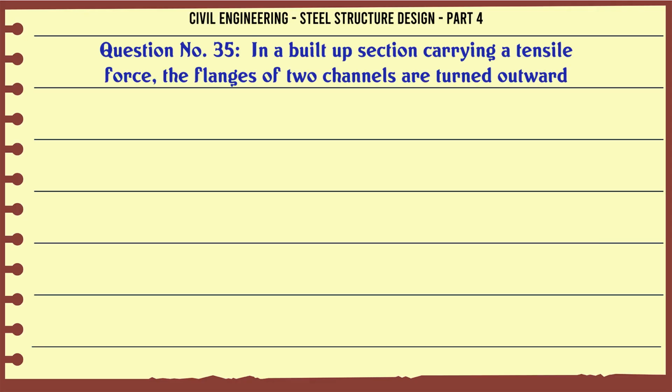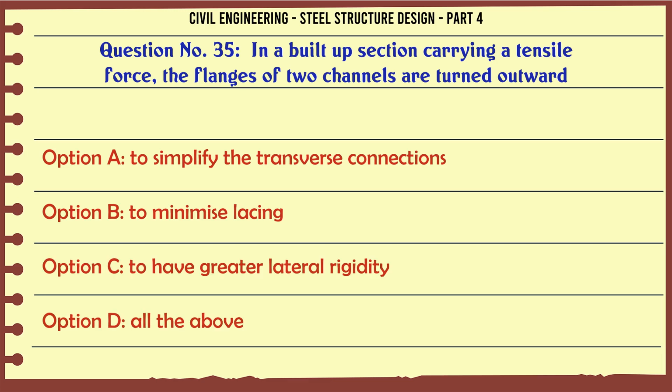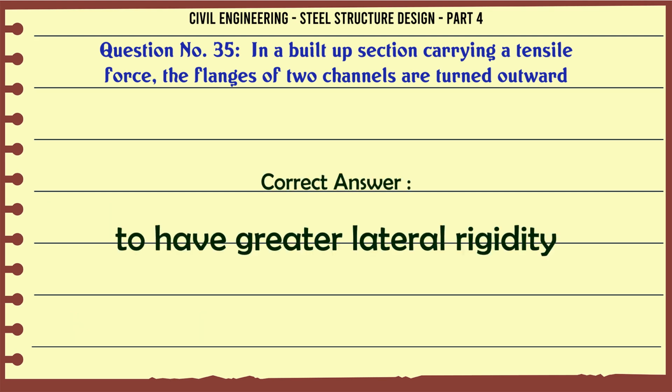In a built-up section carrying a tensile force, the flanges of two channels are turned outward A. to simplify the transverse connections, B. to minimize lacing, C. to have greater lateral rigidity, D. all the above. The correct answer is to have greater lateral rigidity.